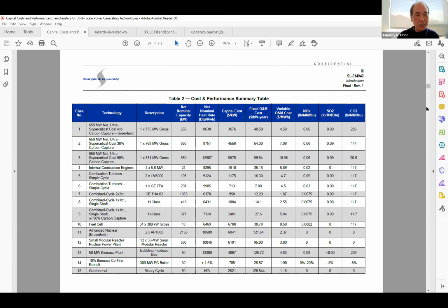So I'm going to take the fixed cost and multiply it by the nominal capacity, which now is in megawatts, not in kilowatts. And that'll give me my annual fixed O&M cost. And that's going to be a part of C1, not half, but a part of it. Oh, is it going to be 1 plus the discount to the power? It is. Now that'll be the denominator.